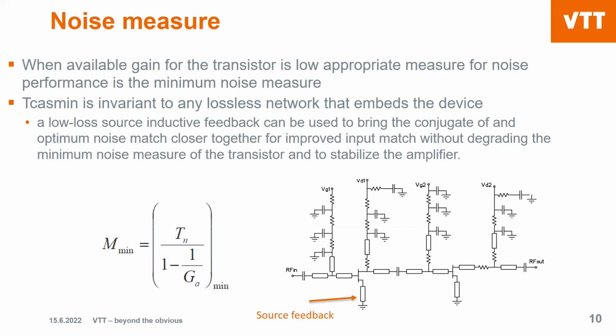And what we do is move on a Smith chart to the correct place. We are in trouble if the system requires super low power consumption and wide bandwidth, because then we cannot move on the Smith chart. Putting fingers in parallel means that we burn more power all the time to move on the Smith chart.